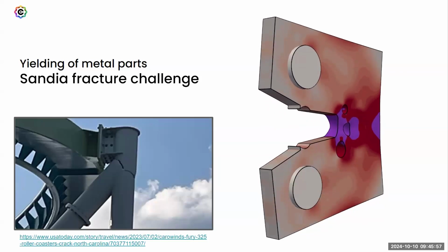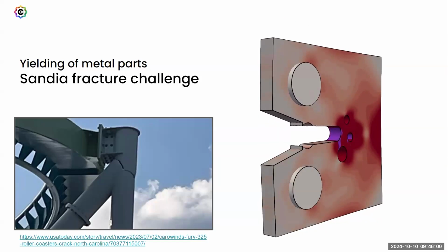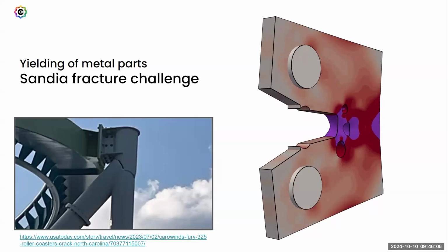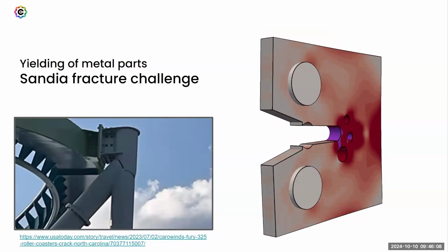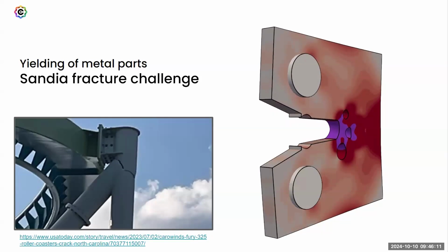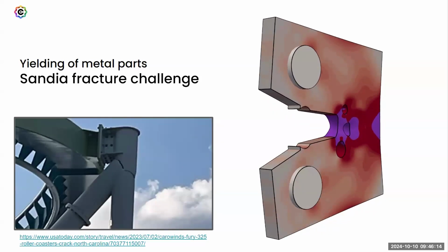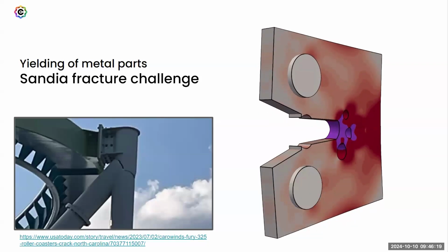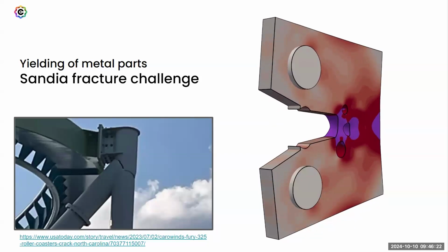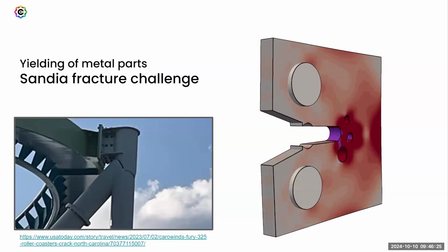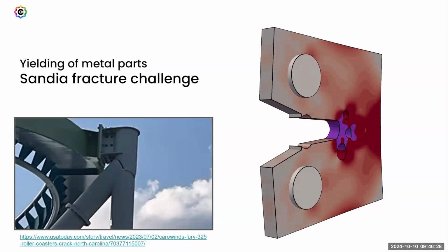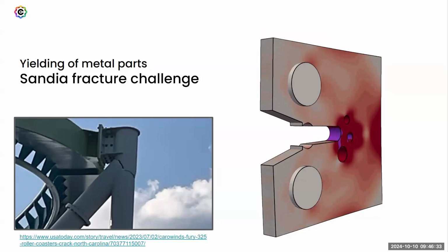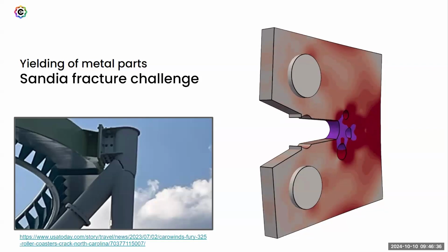Another question from Young: does Coreform Flex support all element types commonly used in traditional FEA software? And is it capable of analyzing structures that contain a combination of shell, solid, and beam elements? Yeah, so Coreform Flex today only supports solid elements. The flex representation method that we've developed does support all of the different dimensionalities of elements with the same trimming approach. So that is a very general thing that is supported by the underlying technology, but we have not implemented those